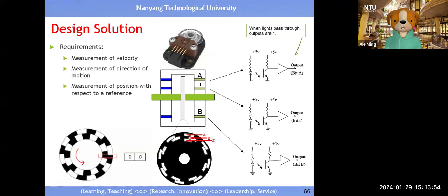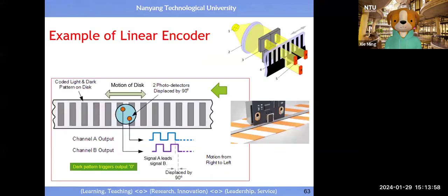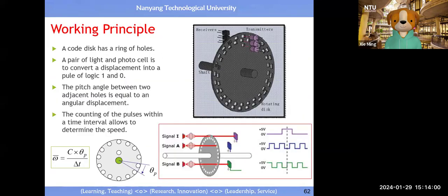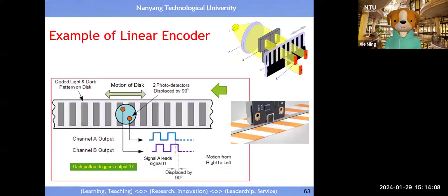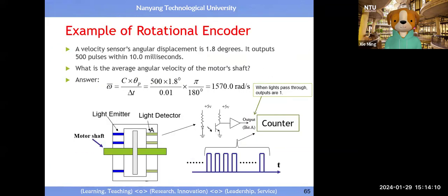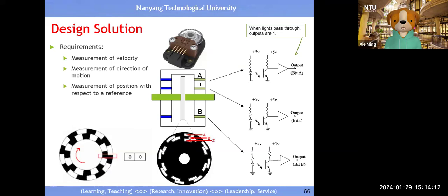You see, you have a one here, and here also you see R. Here you see a one, right? So that means the signal I, sometimes we call it signal R. And here is R, right? So that is the position in between. This is the zero position. At this point, you can start to do the integration. Then you can get the position information.